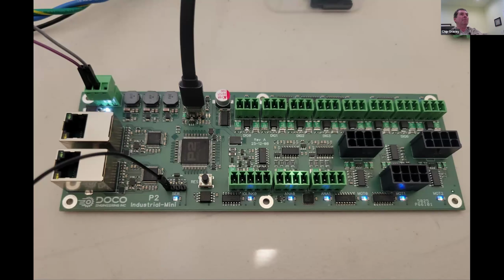Also, this black part here, that's a TVS, a transient voltage suppressor. There's all kinds of protection diodes and fuses, so that if they completely screw this thing up and hook up a 24 volt output to some 5 volt input signal, it's not going to damage anything, because everything is protected through all these little fuses, and then through transient voltage suppressors, which can help open the fuses in miswiring situations.